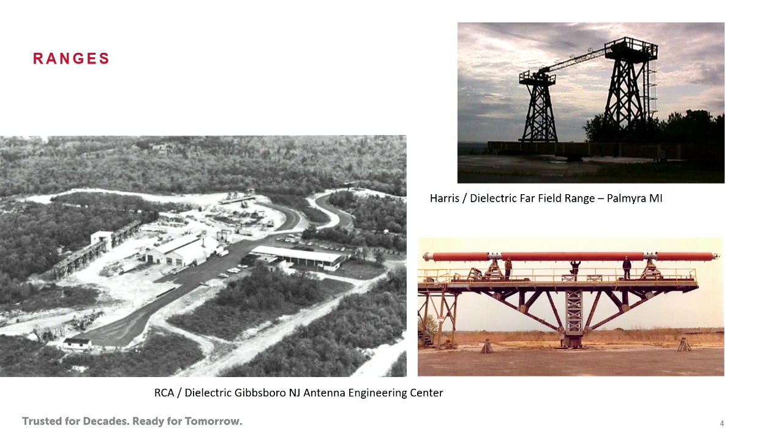The reason for that is you've got to make sure you're doing far field measurements, right? If you want them to be accurate, you've got to get far enough away from the elevation pattern specifically to get a good far field measurement. There's a picture there, the Palmyra picture that was on the previous slide as well. And you'll notice here the antenna is horizontal. No, we don't install them that way.